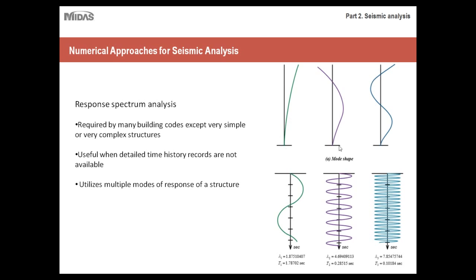For example, if you only design for this mode or only for this mode, and neglect these previous two, you'd essentially be designing your building to withstand one portion of the earthquake but not the other. That's why taking all of these modes into account is very important, to cover critical loading conditions for various points of the earthquake.